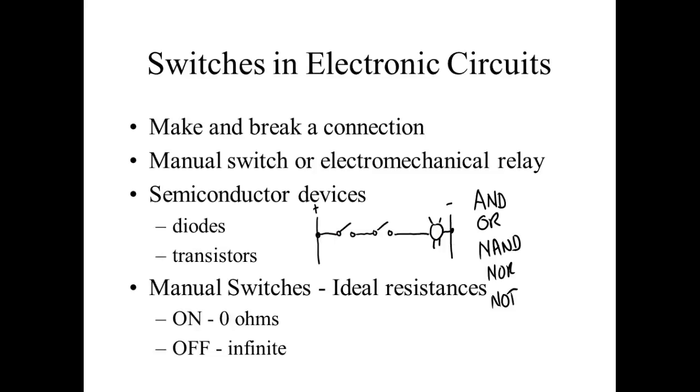So when does the light come on? I'm going to call this 1, and I'm going to call this 2. Well, let's use one of these logic terms. Let's not say both. There's no both over here. Which one would you say? You'd say when 1 and 2 are closed. That makes sense? So this is AND logic. It's been around for years.